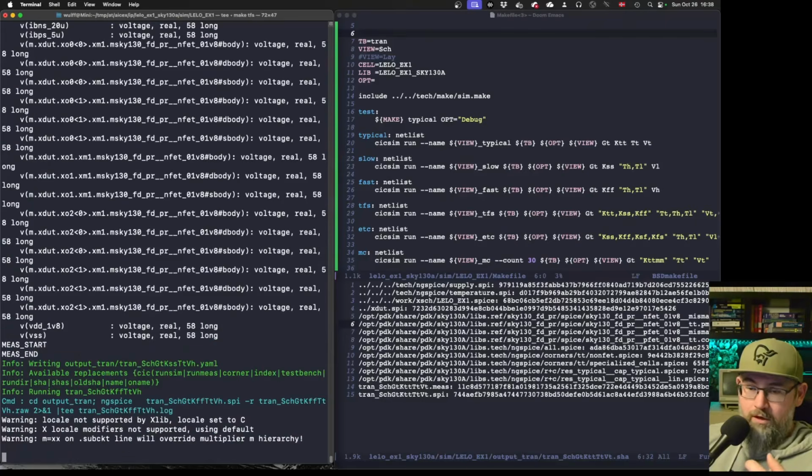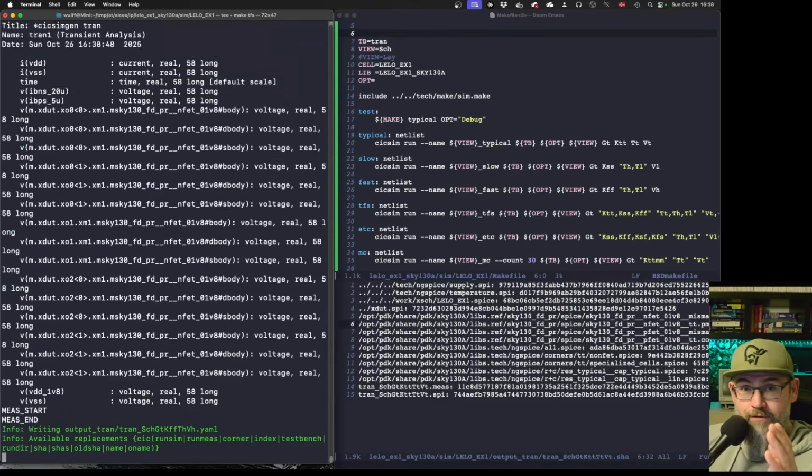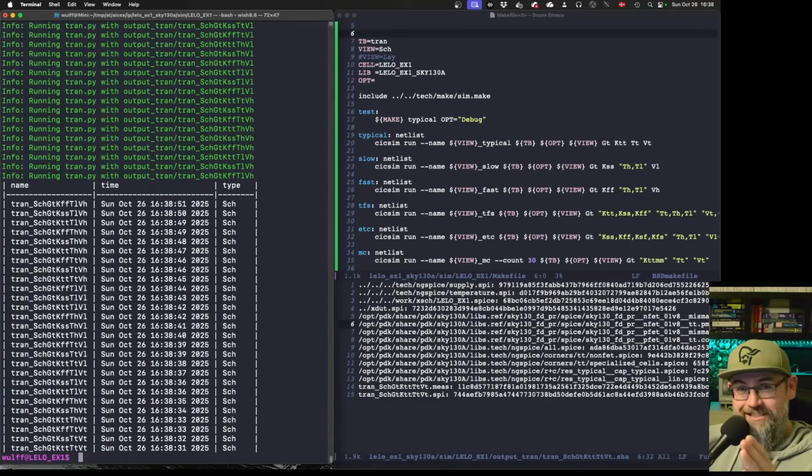Usually, for example, an ingot of silicon is cut into thin slices where you have the wafer. And that wafer has a certain intrinsic resistivity. That's because when you make the ingot, you mix in the dopants and you grow this ingot and you're turning it and so on and so forth. And when you cut the wafers, you end up with different resistivity. That resistivity might impact your transistor. Probably doesn't to a large degree, but maybe a little bit.